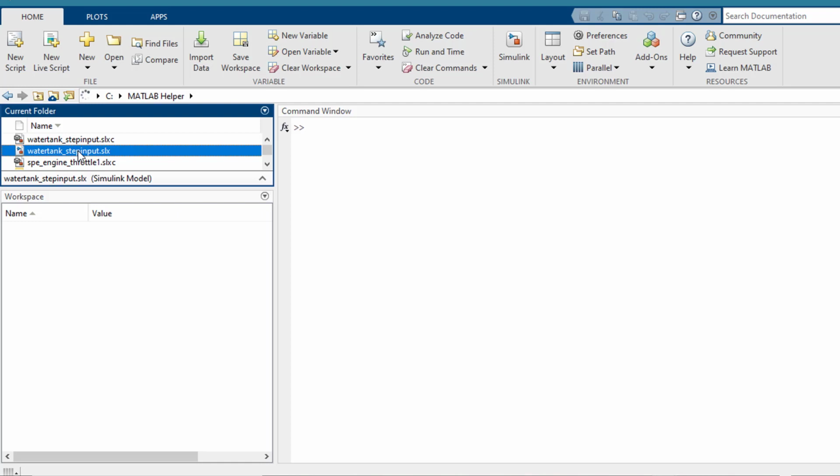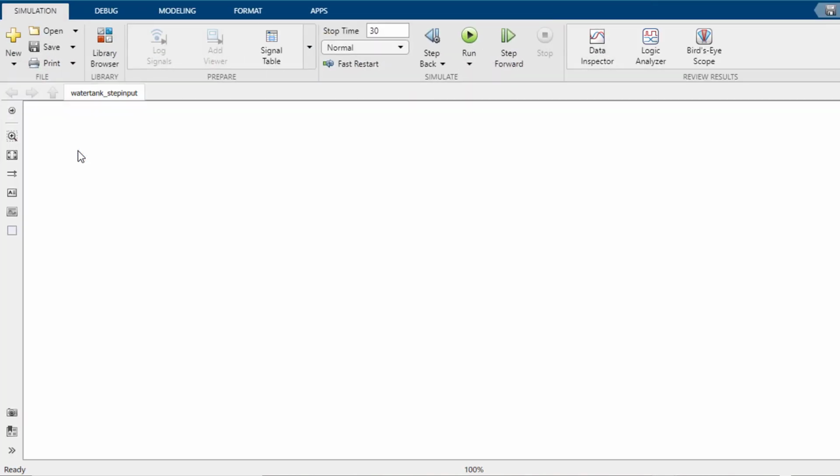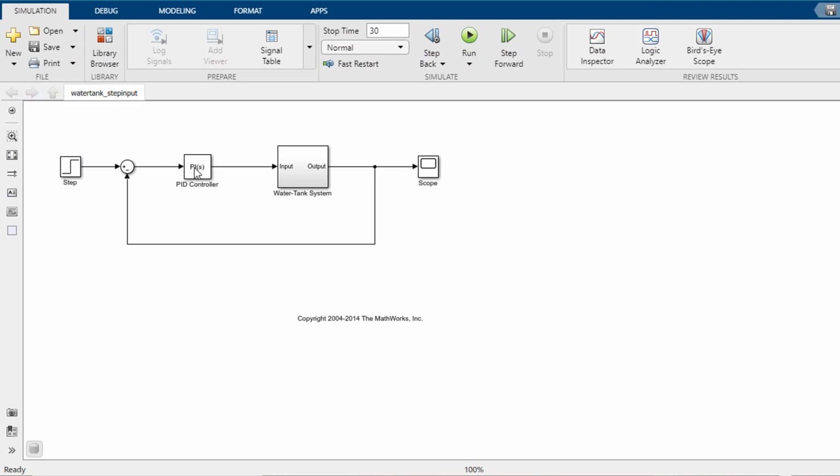This is a non-linear model with a PI controller, and in this case we are using response optimization for estimating the correct values of this controller to get a better response. This response should be according to our time domain requirements like overshoot and settling time. So let's see the model.